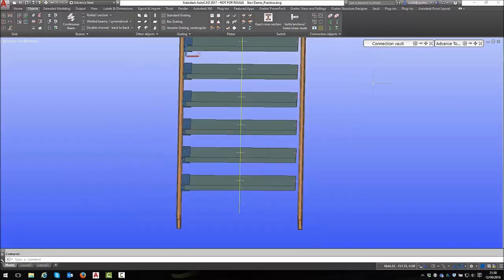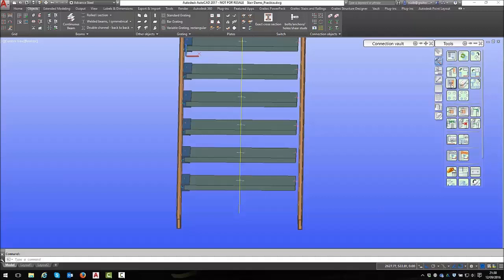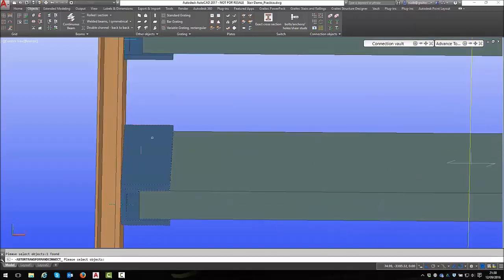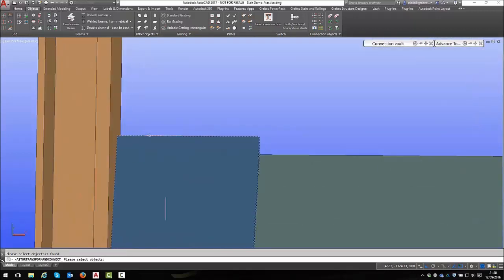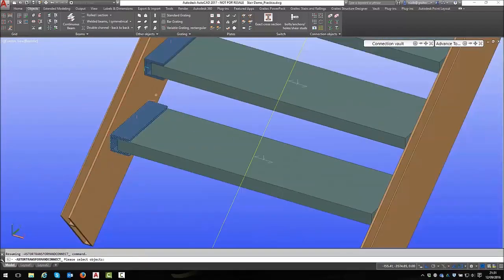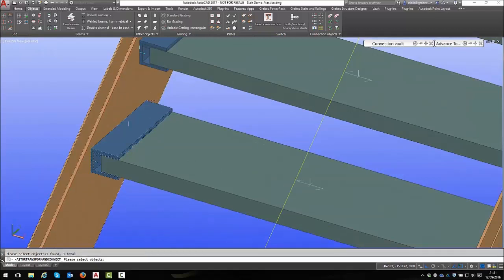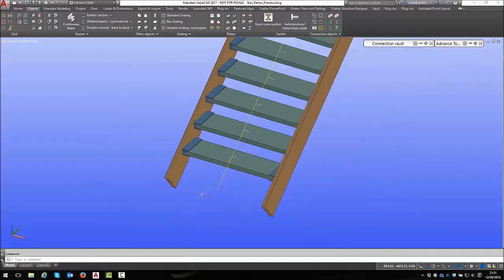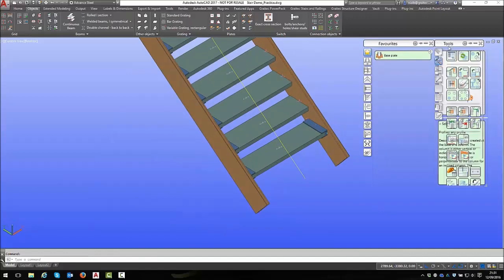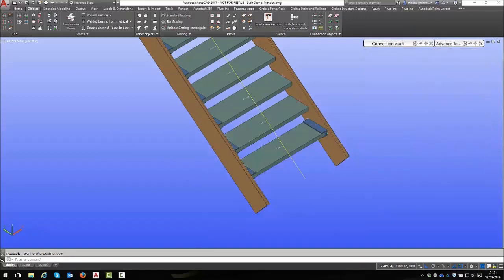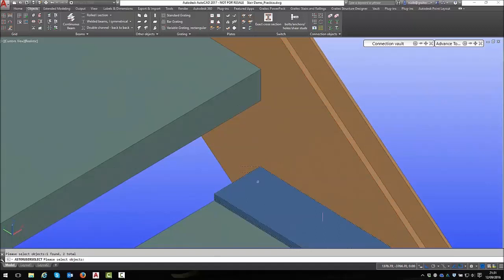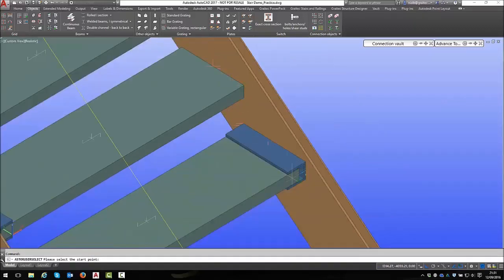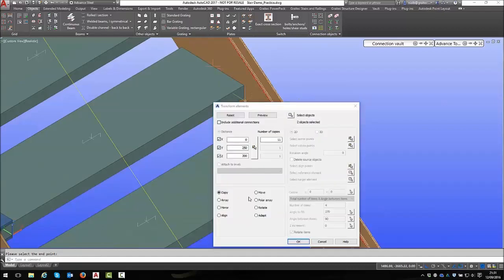I'm going to mirror this, so I'm just going to mirror the one. This is the advanced mirror tool. I'm going to mirror this and the weld. See if I can get that. There it is. I think I got it. Yes. Definitely have now. Okay, I'm going to mirror this. I can go from the midpoint here, straight out, right click, there it is. And again, transform elements, select the objects, 1, 2, and I'm going to copy that from here to here again.